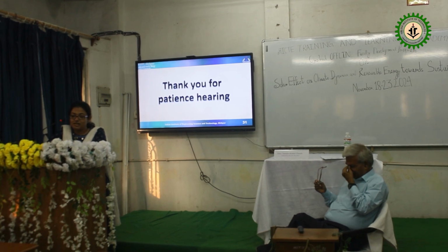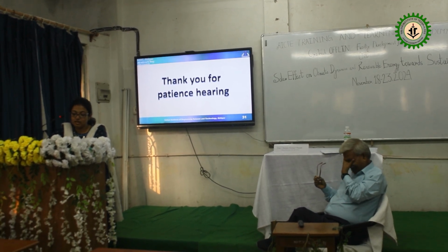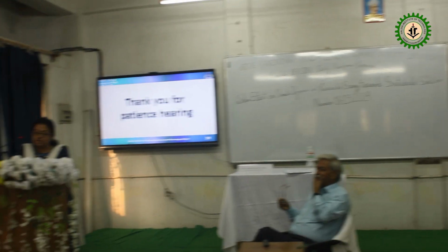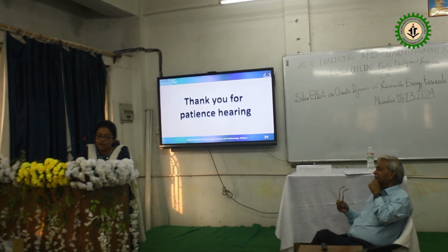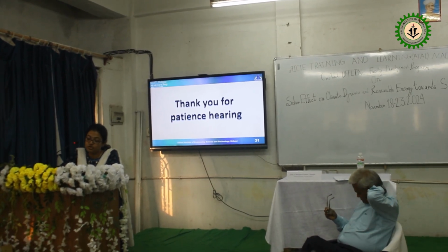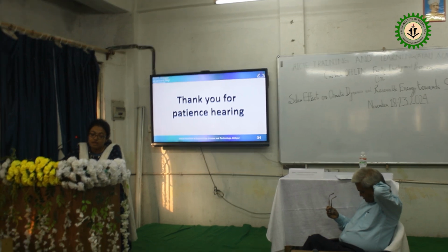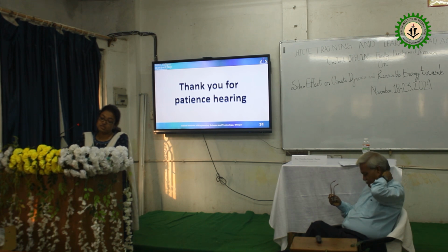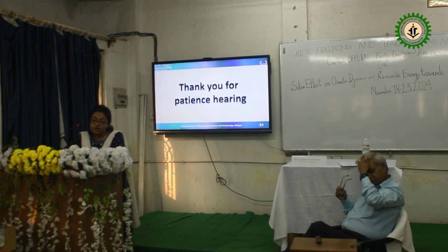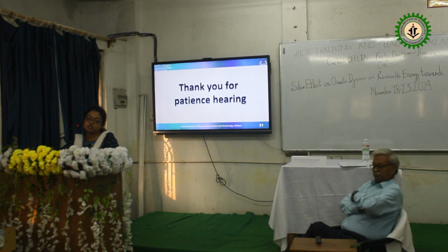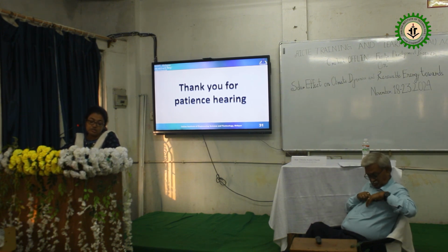This session highlighted several challenges associated with renewable energy integration, including reduced system inertia, increased frequency variability, and the limitations of non-synchronous technologies. It emphasized the crucial role of inertia in stabilizing the power grid, particularly as the industry transitions from mechanical to virtual solutions in renewable systems.